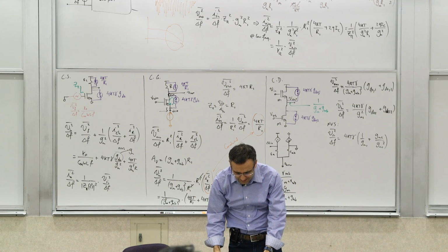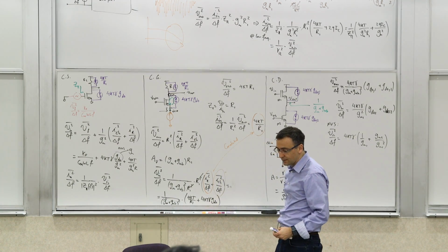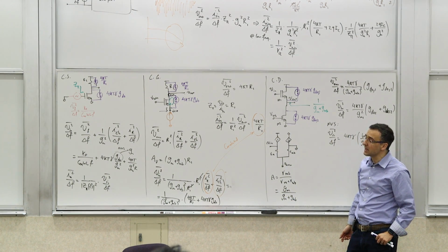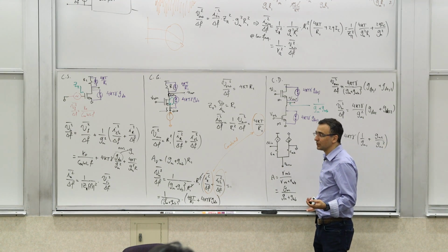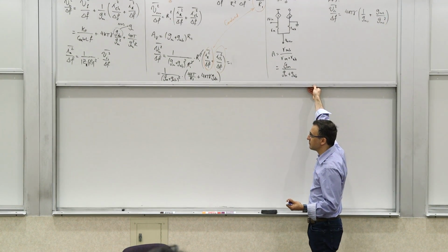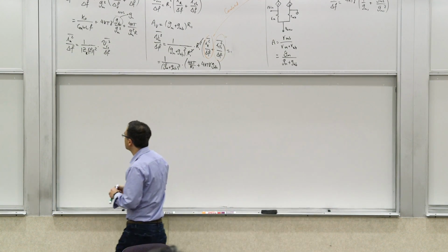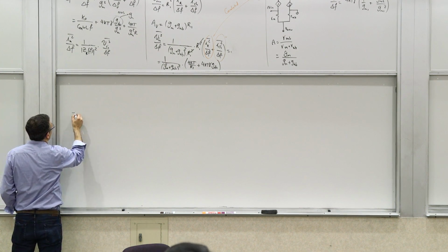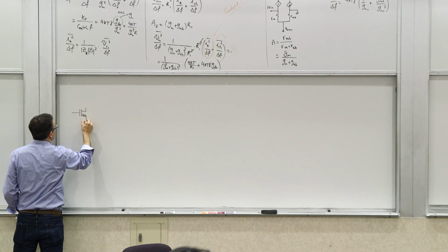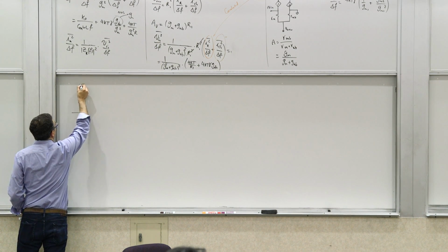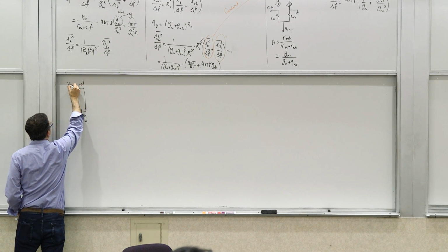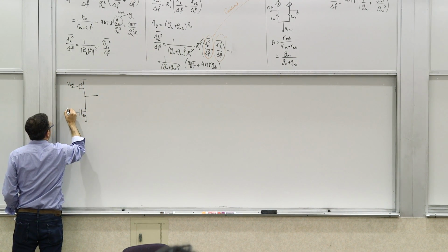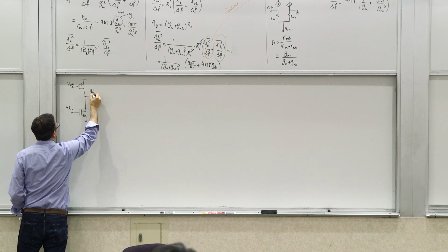One more quick example of this system in a scenario that you actually have, let's say, an active load. Let's say a situation where you'll have a common source, but now you have an active load. We see this scenario frequently when you are designing high-gain amplifiers, right? So in one scenario, you can have an NMOS here and a PMOS there, which is biased somehow. We know how to do these things. We've done a lot of those before. And then you have V in and V out.